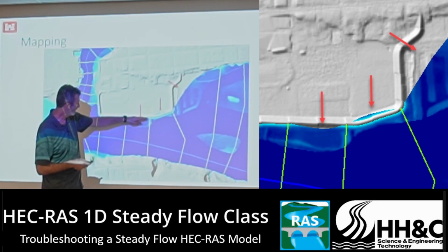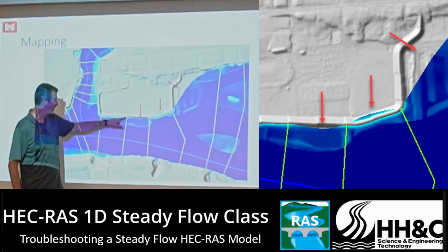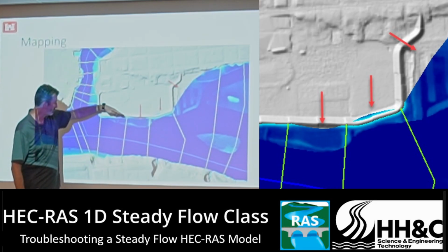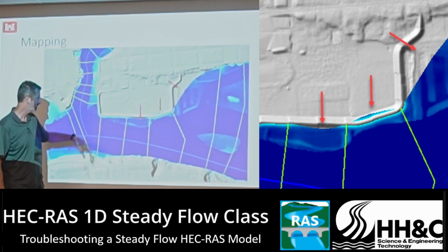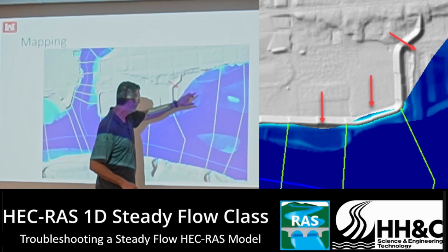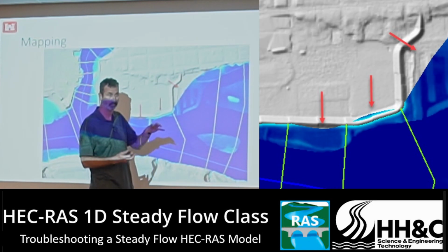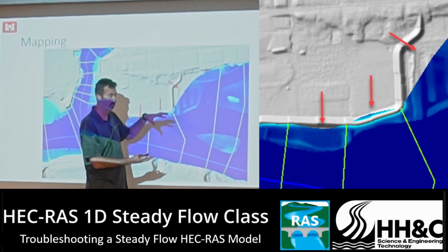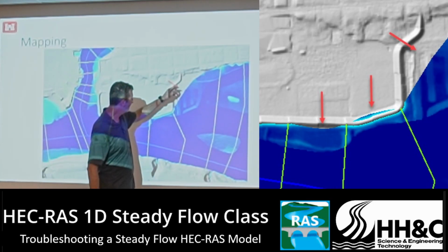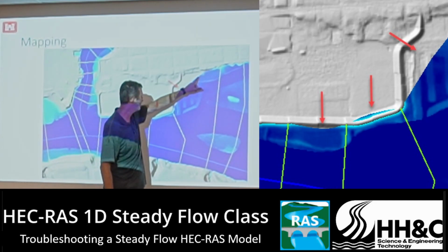In this case, we'd want to move this edge out over there, because the program during the simulation will make a zone, the bounds of where water can go from cross section to cross section. And over here, it's even more dramatic, that your cross section line went from there to there, and then it makes a TIN to cover that area, which will then be used to fill in this with water surface. And I didn't know about the terrain over here, so I just made a line that followed something like that.